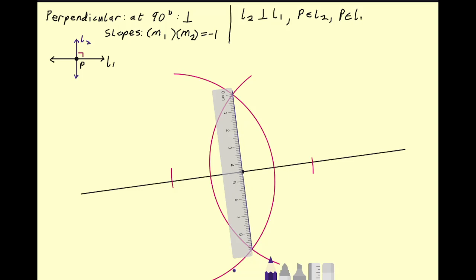I must get the perpendicular bisector between those two original arcs that I created out here, and this purple line here is a line that is going to be perpendicular to our original line, and it is going to go through our point that we were interested in, because we deliberately created our arcs out here to give us the point we were interested in as the midpoint. So that's how we can construct our line using a compass and a straight edge.